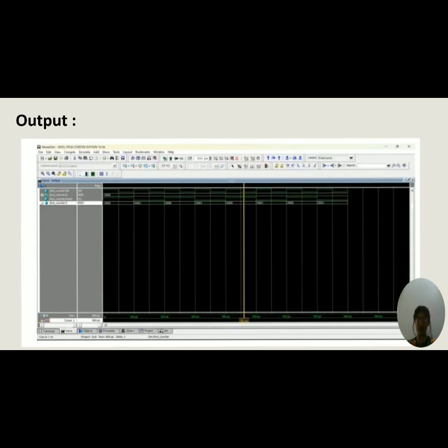Look at this output. It is a 4-bit BCD counter sequence counting from 0 to 9 repeatedly. How it works is that initially the reset signal is asserted, which sets T and Q equal to 0. On each positive edge of the clock, the T register increments by 1, and as it reaches 9, it resets back to 0, and this implements the BCD counter behavior. The value stored in T is continuously assigned to the output Q, and this represents the current count value.